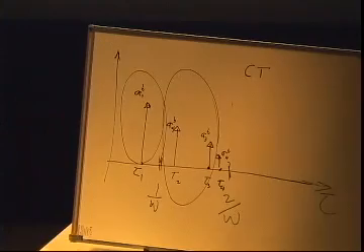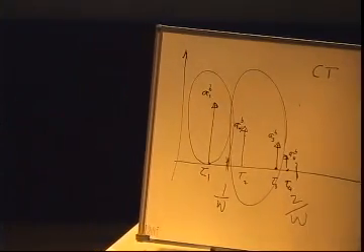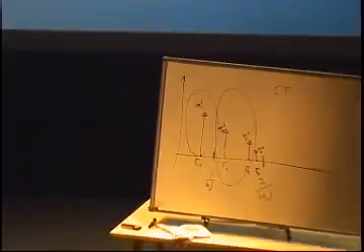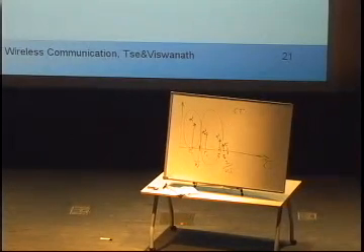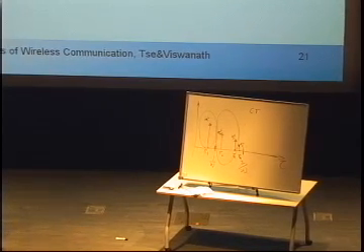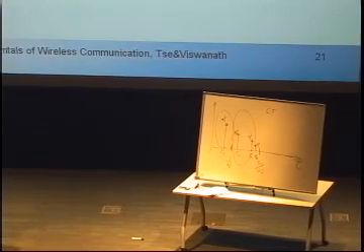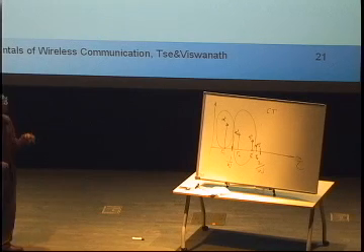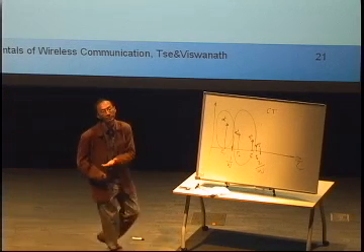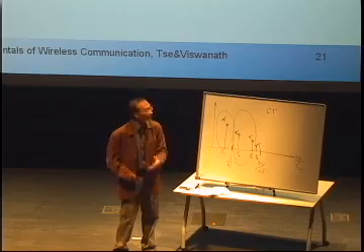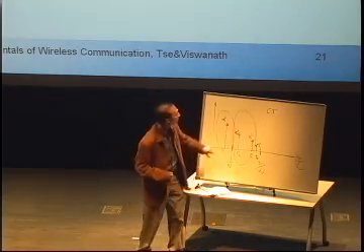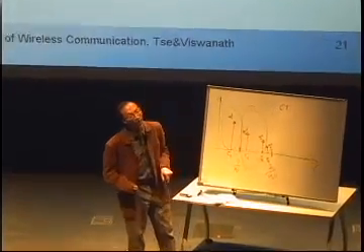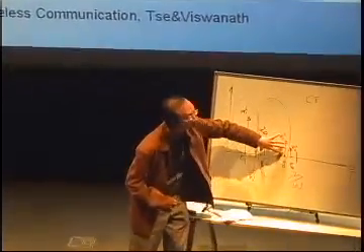Remember, fading comes from destructive interference of signals. If I see each one individually, there's no fading. I have access to the signals coming from individual paths, and I can do whatever processing. The fact that we have fading is because we have a limit in bandwidth, and therefore we cannot resolve some of these paths. This one maybe we can resolve, so it's good. But these guys, we cannot resolve.